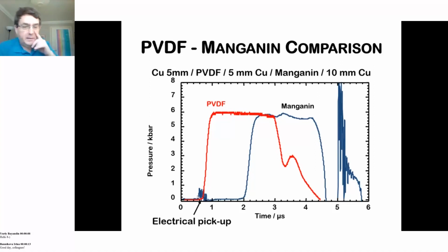What you will see is, because PVDF releases charge, and because stress gauges such as manganin have an antenna, a kind of electrical receiver-like shape to them, they've got these coils of metal there, you will get electrical pickup between the PVDF and manganin. This can be useful for time of arrival if you're interested in such things.